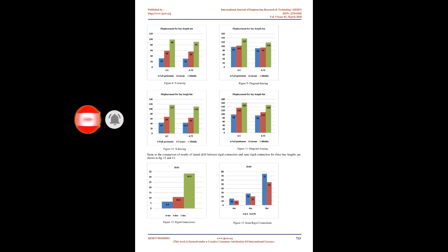Apart from this analysis, this research widely investigates the comparative analysis of semi-rigid connection with or without bracing system. As per convenience, X bracing and diagonal bracing are used at different locations of the periphery of the structure. The primary aim of this study is to compare the two types of partial release condition as per the fixity factor equation. Fixity factor is considered 0 for ideally pinned conditions and 1 for rigid conditions in the analysis of the frame.